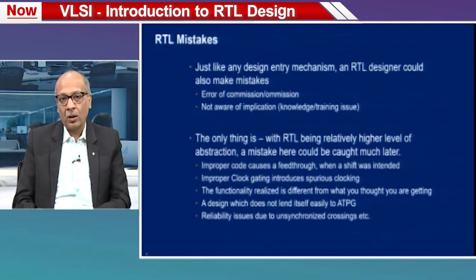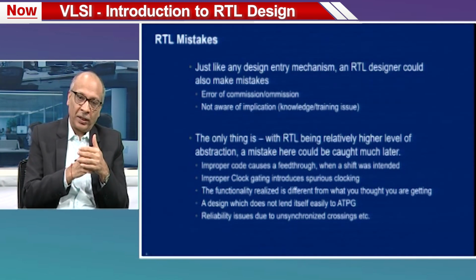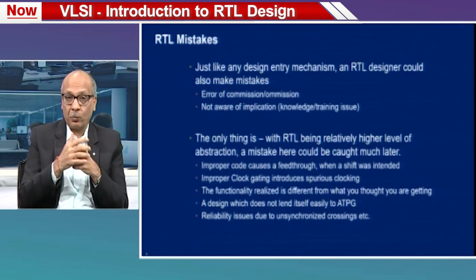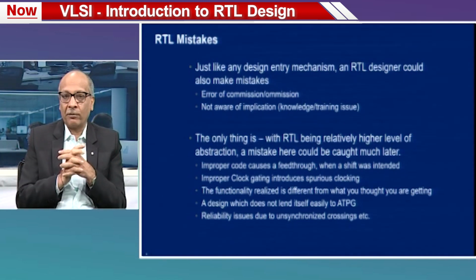Or somebody could do clock gating which is not done correctly. If clock gating is not done correctly, then what happens is something called spurious clocking, which means clocks will start showing up at a place where they should not show up.